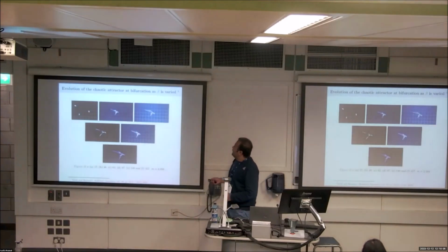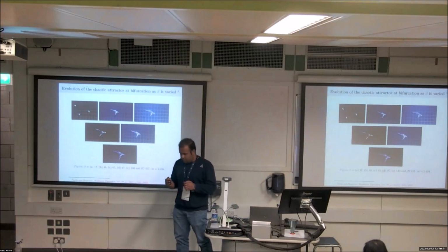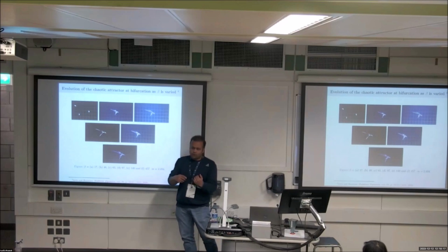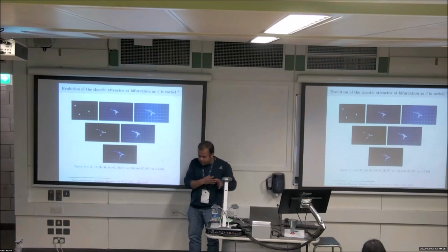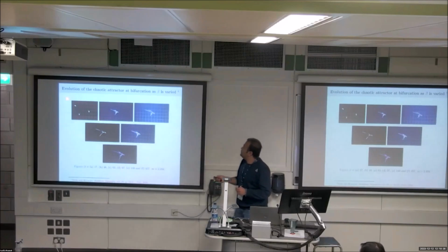Then we have done another type of work. We are now varying the capacitor voltage, which is added as a parallel capacitive branch, which is similar to changing the stiffness value from low to high, making the stiffness ratio go from low to high, which means from very soft impact to hard impact. When the stiffness ratio is very small, you will find there is a period 3 orbit. This is the Poincare representation, where the x-axis is the current and the y-axis is the voltage across the capacitor.